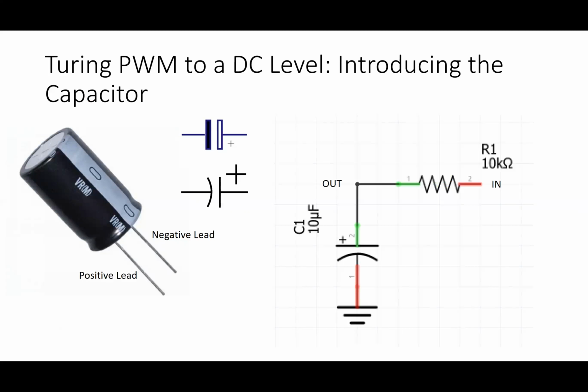How can we make an electronic equivalent of our slow eyeball? Well, there's a component for doing that, and it's called a capacitor. And in particular, we want a large capacitor, so it's called a polarized or electrolytic capacitor. Because it's polarized, it has different colors associated with each side of it. So a white bar and a black bar with a plus sign here, or sometimes a straight bar and a curly bar with a plus sign here.